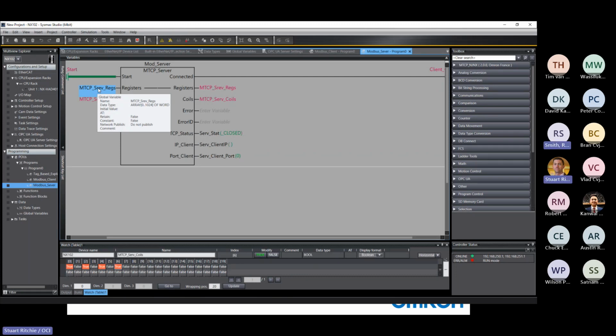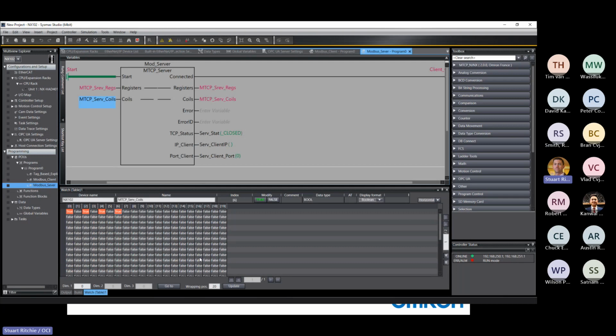Okay. So we just have to populate the registers and the coil data. Exactly. And so coil number 123 is array index 123. So we ignore the first, like the 10,000, 20,000, 30,000, 40,000 type thing. We'll take care of appending that in the background. But yeah, 1 to 1, 5 is 5. Yeah, that's pretty sharp.